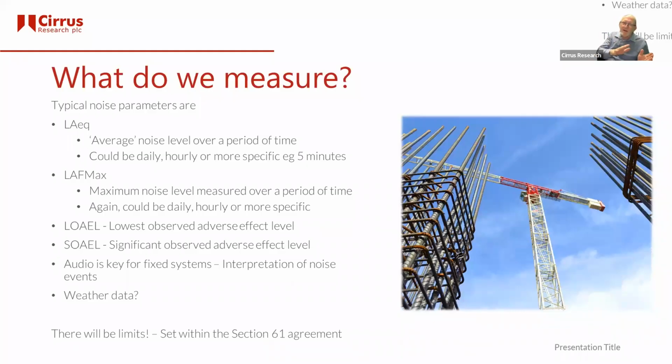The other thing we're looking at, and it's not as common, but some councils insist on this, is the LAFmax. So it's the A-weighted fast time constant maximum noise level during a period of time. So you'd want to know what was the maximum level every 5 minutes, or every hour. So the average is telling you something, but the maximum level will tell you something as well. That maximum might be fairly instantaneous.